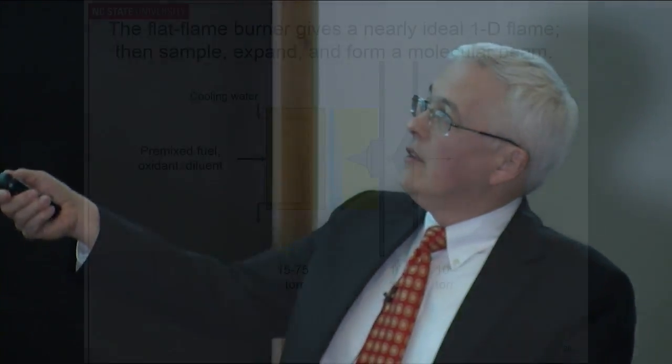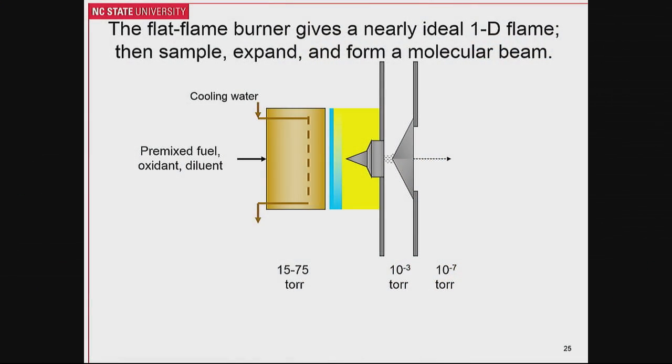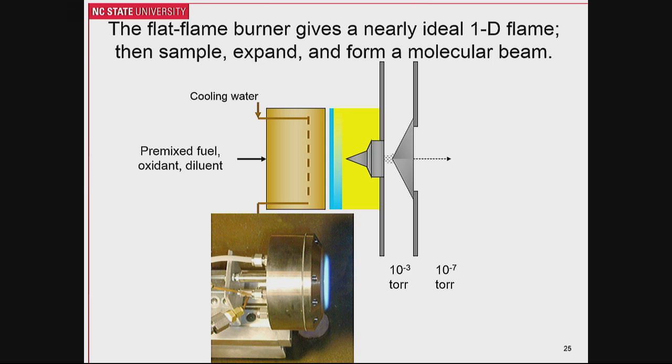So to create that experimentally is a so-called flat flame burner run at low pressures. Here's a physical realization of it. You see a flame burning on the surface, not very thick, but by operating at low pressures, we can expand it physically enough to be able to do gas sampling, not by moving a probe, but by moving the burner and the flame relative to the probe.